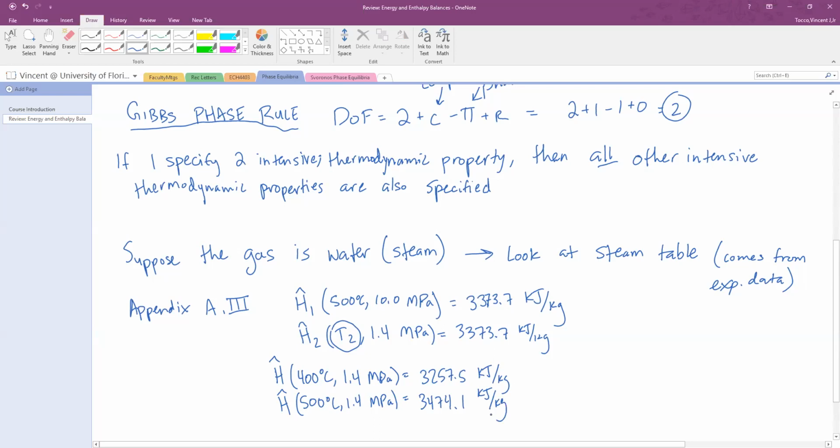In cases like this, it's typically appropriate to interpolate. So if I assume that the data is exactly linear between these 2 points, that will give me an approximation. Now this ruins some of the accuracy of the steam tables, of course, because now you're approximating a little bit. So you wouldn't say that the steam table is always the best, because sometimes you have to interpolate nonlinear data and pretend that it's linear. But the approximations that it gives you won't be too bad.